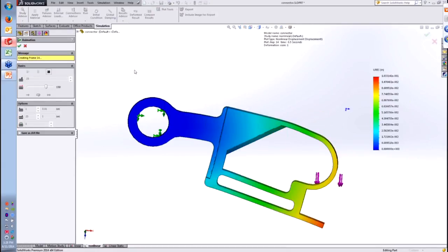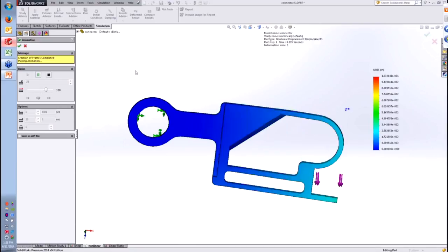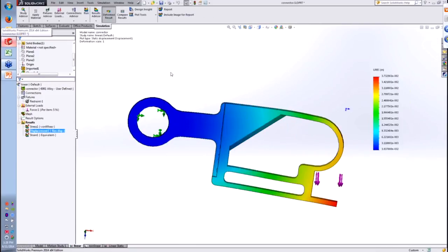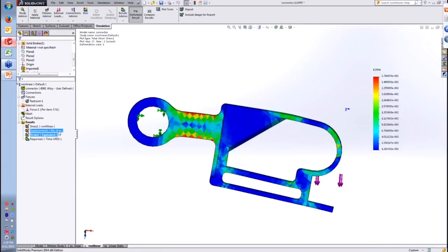And this is showing that the maximum displacement is about 0.103 inches, whereas the linear study predicted a maximum displacement of about 0.03 inches. So again, that was not an accurate result. Of course, we can also view what the strain of the model is and see what this permanent strain looks like after the load's been completely removed, which in this case is at the end of this 1 second time period.